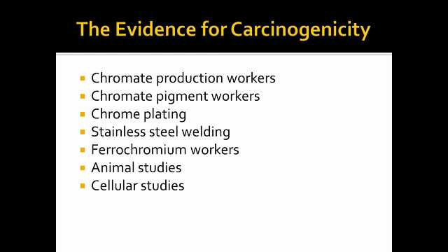So before we start talking about where we find hexchrome in foundries, I want to just kind of lay a little groundwork here. I'm going to talk first about the OSHA exposure limits because I want to talk about those as we go along and discuss exposures in foundries, and then we'll get into the standard itself. But the permissible exposure limit is 5 micrograms per cubic meter. That's a pretty low number. The action level is 2.5 micrograms per cubic meter. And then the trigger level for the standards provisions is 0.5 micrograms per cubic meter. If you have exposures that are under 0.5, the standard actually doesn't even apply to your situation. And we'll talk about that in a few minutes again.